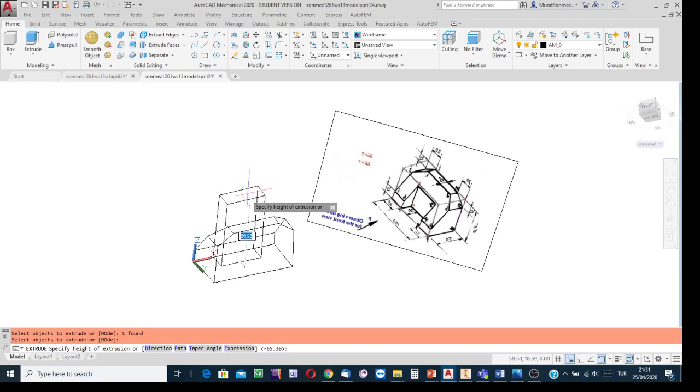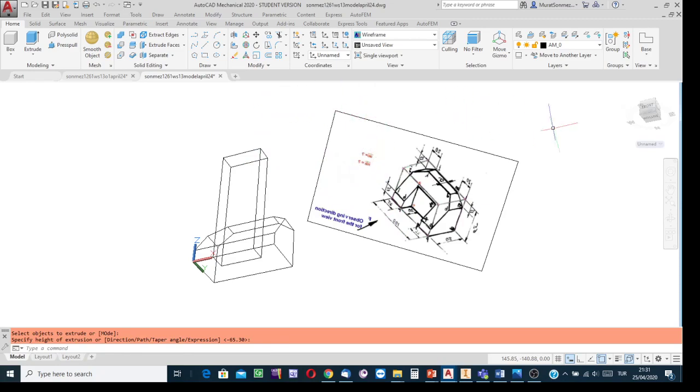From the bottom side surface to a higher point, create the prism. The length of the rectangular prism is not so important, but it should be higher than the height of the channel. I am sure that if I create it with further extension beyond the limit of the part, I can create the channel by subtracting.